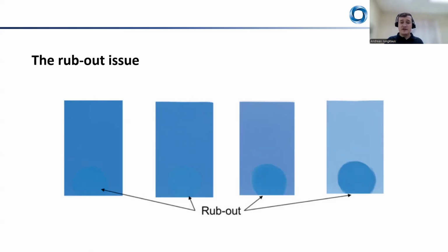So when part of a freshly applied paint film is rubbed, the mechanical action of rubbing improves local pigment wetting and dispersion. And if the original formulation lacks sufficient wetting agent, the rubbed area will show a noticeable color or gloss difference compared to the untouched area.